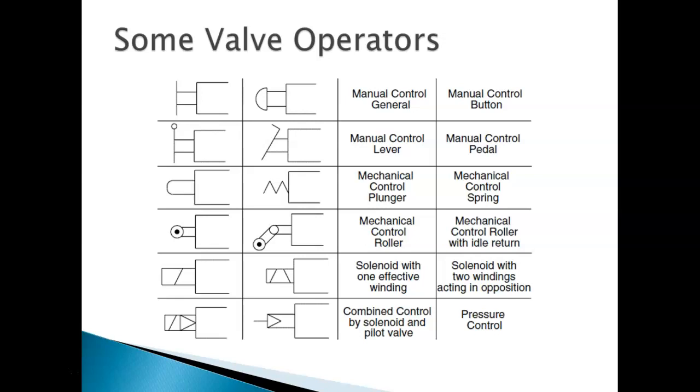So then, whenever we're dealing with these symbols, we also have to deal with what the operators are. This particular one is a detent switch. What that means is that whenever I turn the switch, it locks in place until I come back and pop it loose. So I use a button. You've got somebody that's got to press the button. That means they press and release, right?